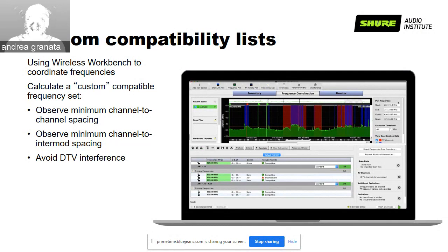I'm not going into antenna placement because this is a topic that will be covered exactly one week from now. What I can tell you is that it depends very much on the LED screen. But in general, all the LED screens are emitting louder at the back than in the front. Sorry, a little water. So do not ever place the antennas at the back of the LED. Try always to keep them in the front. Use directivity. And we will continue discussing the topic next week when we will cover antennas and cabling.